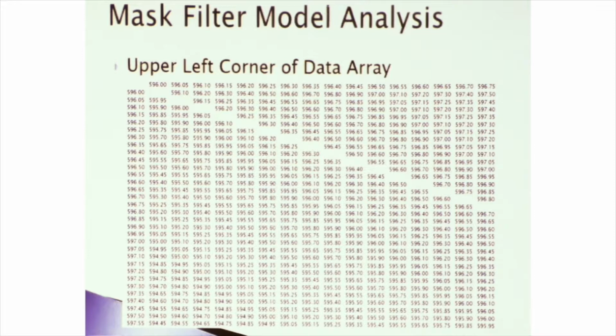So part of what goes on when you generate intermod is that you have, if this is the spectrum of the channel, and this is what we're looking at here. So here's 596, and here's 602, the ends of that channel. Every point in the spectrum here intermodulates with every other point in the spectrum.